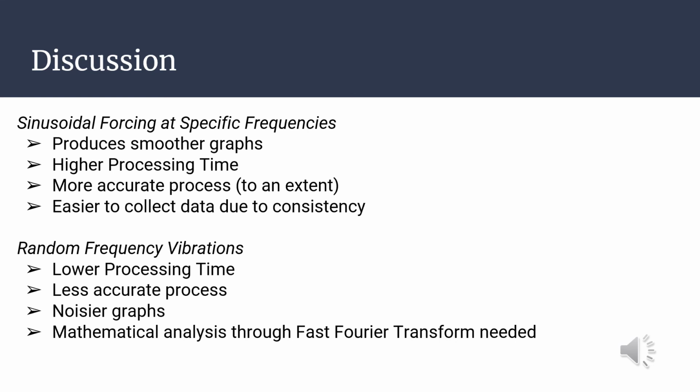A downside to random frequency vibrations is that there's a need for mathematical analysis through fast Fourier transform, where it is easier to just pick points on a sinusoidal forcing.